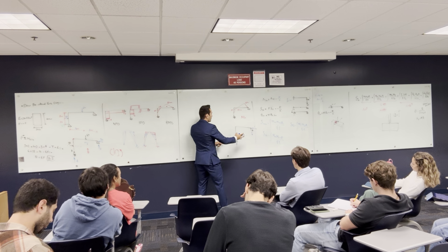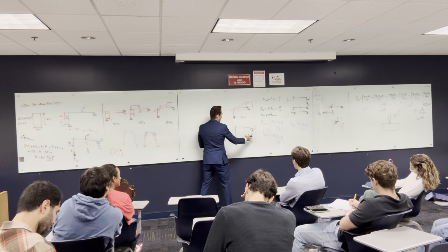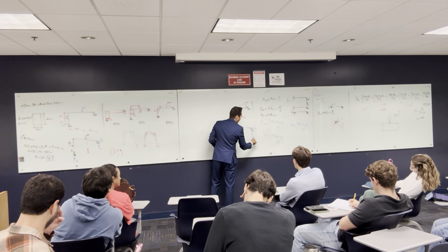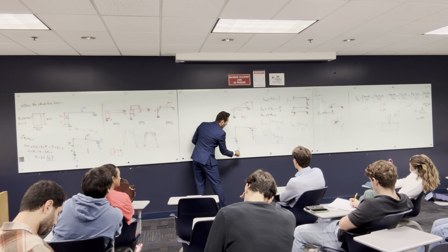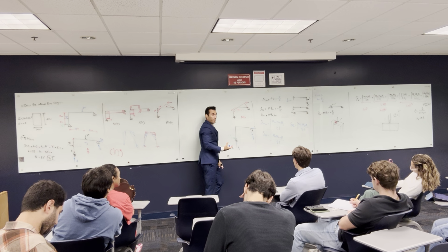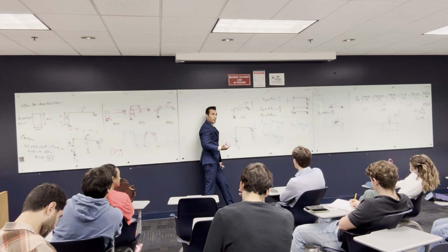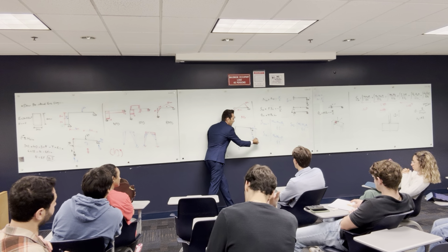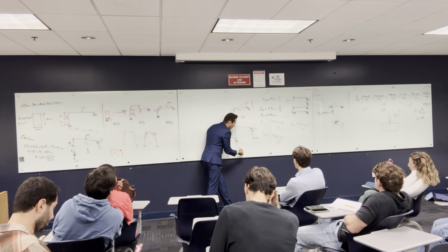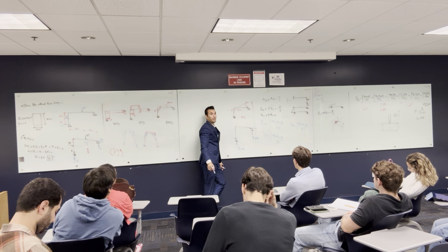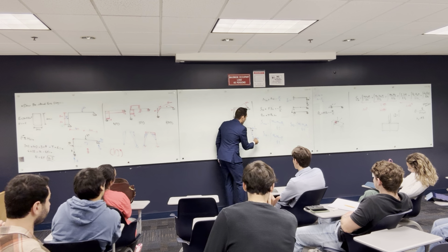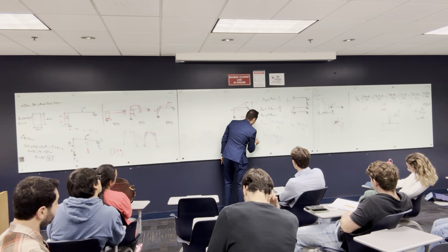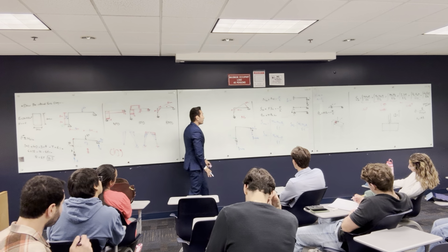This generates 4, and the distance is 6, so this is going to be 4/6 and this is 4/6. If you want the right value, do the equilibrium equation. Take the moment here equal to 0, and the reactions are 0.67 and 0.67. Here this value is negative, and this value is positive. So I got the reactions.